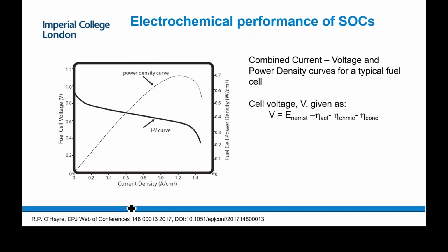You can't get much higher than that. Okay, you can then calculate your power density. So looking at current density, looking at power density. You're getting the maximum power density is where you want to be operating your cell. But in this particular example, your maximum power density is getting perilously close to this area where you have this drop-off in performance in the IV curve.